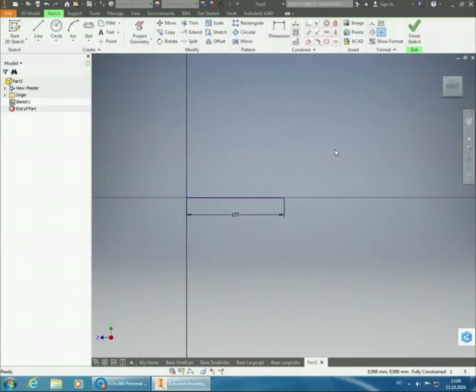And we're basically going to do the same as we did for this one when we created these rounded edges. We're going to create just a circle showing this rounded edge. And it has a radius of 30, so we need to do 30 multiplied with 2 to get our diameter. And then we're just going to lock the circle in place using dimensions.